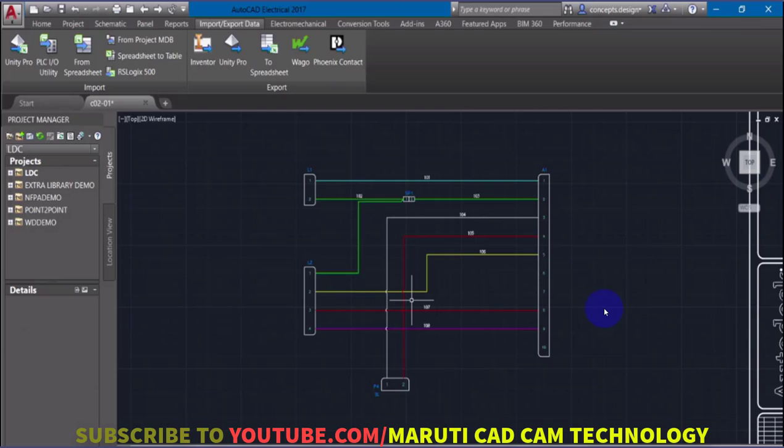To share this information with Inventor, I can simply click on Create File on Export on my active drawing. It is possible to create bidirectional associativity between Inventor and AutoCAD Electrical, so that if any changes are made to the AutoCAD Electrical design or in Inventor, they can also be reflected in the schematic diagram.